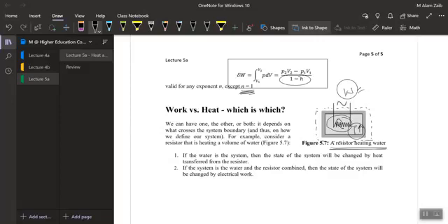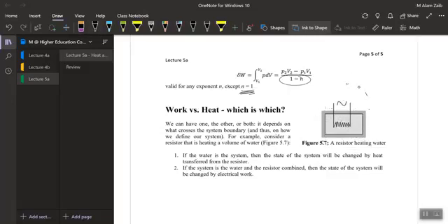Now I would complete this example. If I include this work done as well, it is the same again: the temperature is rising due to the heat supplied, but the heat is transferring due to the work supply. So in other words, the change in the state, which is the change in the temperature of the system, is due to the electrical work which is supplied from above. Let me conclude it again. If your boundary is limited to this bit, not including the work done, you are only limiting yourself to the heat transfer, and that heat transfer is responsible for the rise in temperature.